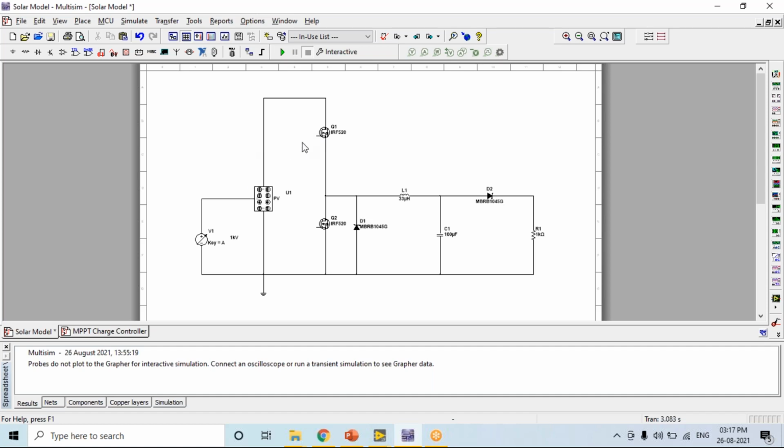But typically it wasn't able to source the total 12 volts. So normally we need an isolated voltage source, like a driver, which should force the voltage, which is always supplied with respect to ground, to instead be generated with respect to source.